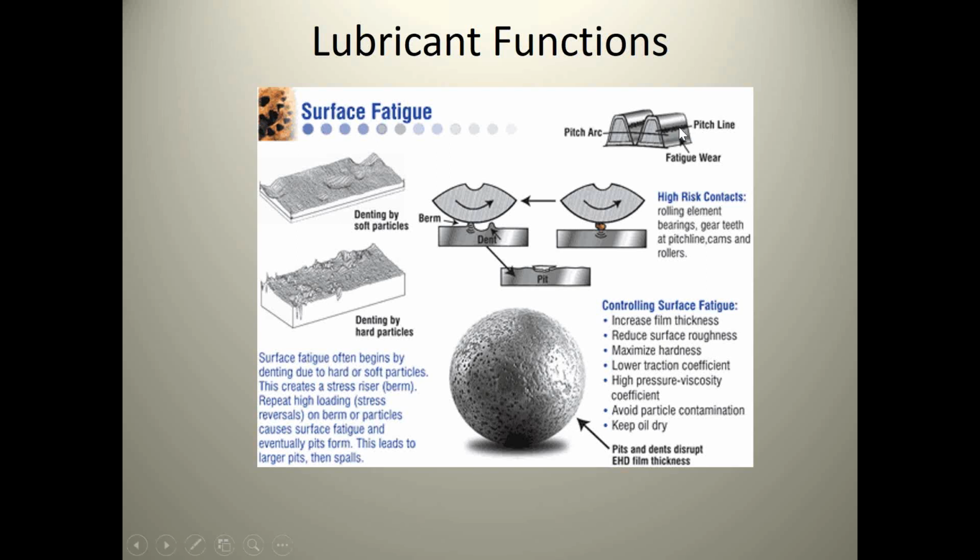If you see the gear line up here in the upper right-hand corner, if you ever look at a gear line and you see pits and cavities on it, more often than not, those started from foreign material particles that were in your lube, and we didn't maintain the lube film. But again, as you start getting the pits and cavities, it's very, very hard to maintain our lube film anymore without damaging the surface even more.